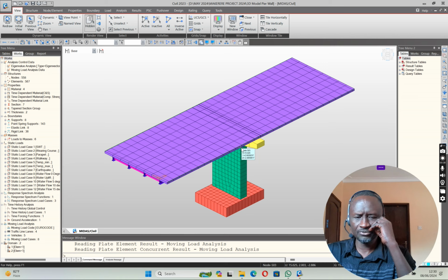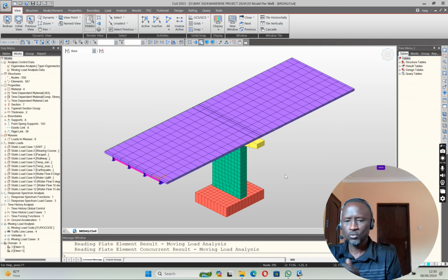Here, I just wanted to demonstrate something in line with the question raised by, I think, Button or someone about consideration of stream flow when you're designing the bridge. Truly, normally for bridges, pier supports are really exposed to high water currents. Therefore, the strength, robustness, size, the depth on a river bed, and orientations are factors you need to look at.